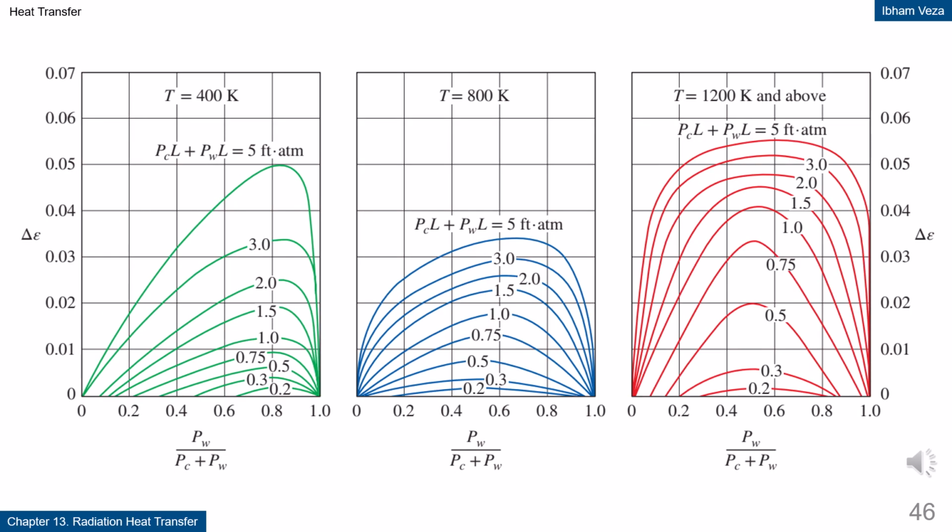Emissivity charts with corrections. Using charts combined with correction factors allows more realistic emissivity estimation. This approach keeps the simplicity of the graphical method. At the same time, the effects of pressure and geometry can be taken into account. This is a compromise between accuracy and computational simplicity. This approach is very commonly used in engineering analysis.